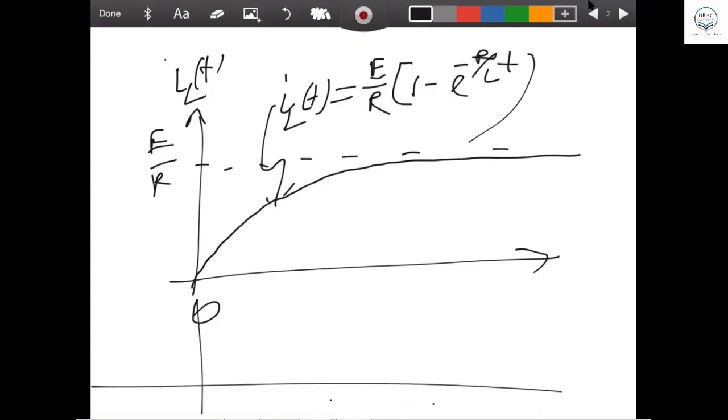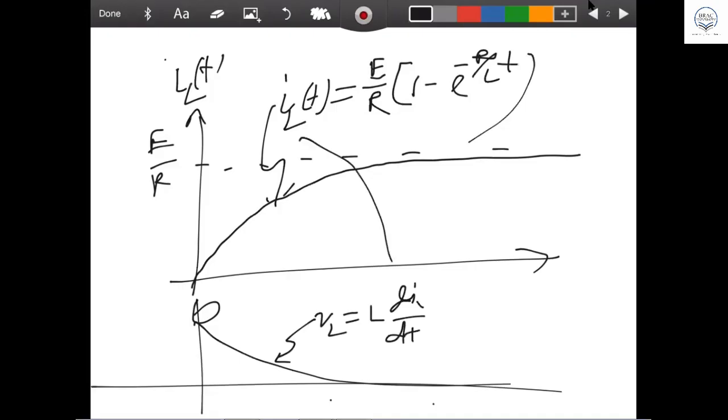Also the voltage curve we have seen, which is VL. You just straight away write L dIL by dt, and the IL value you straight away substitute here, and you get what? I think E to the power minus R by L t. After substitution, all these things, you get something like that, and this is VL(t). Up to this we have done.